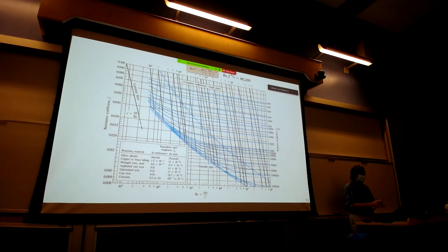Using the computer graphics, I can make it look parallel, but when you're just using your eyeballs, you're just trying to bring that line down parallel between the other 2 black contours. The relative roughness we calculated to be 0.301, and you can see 0.301 on the right vertical axis.